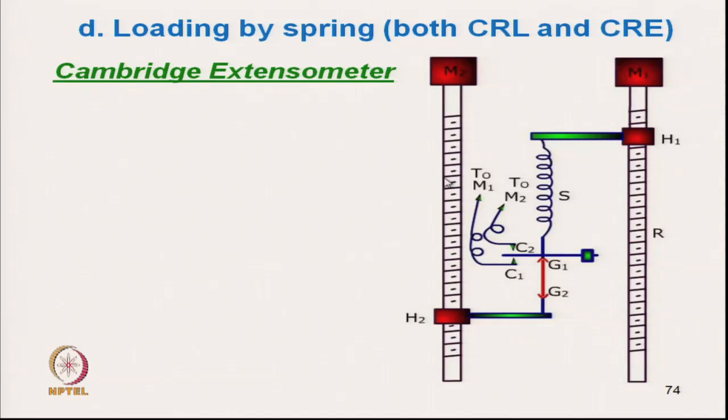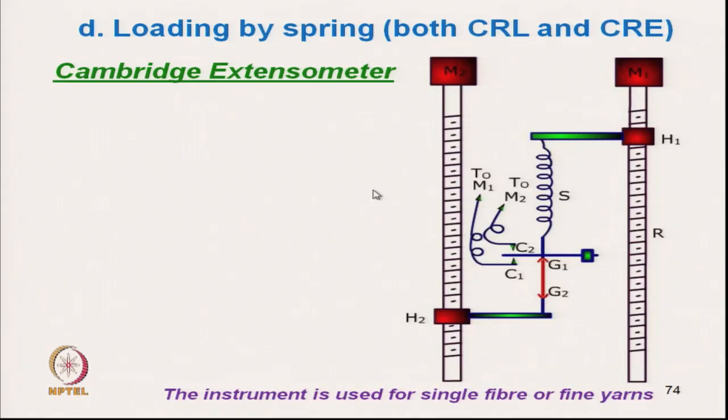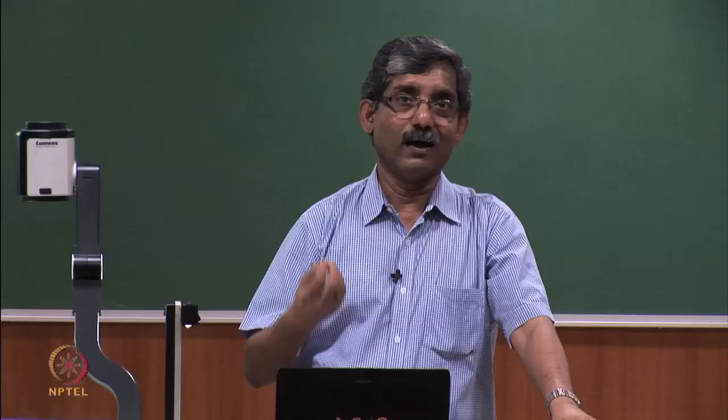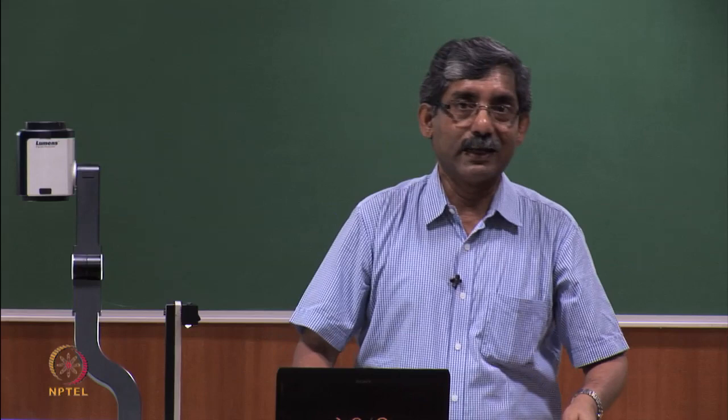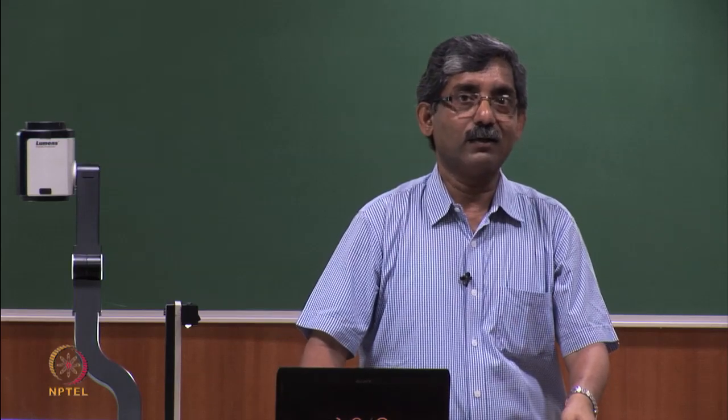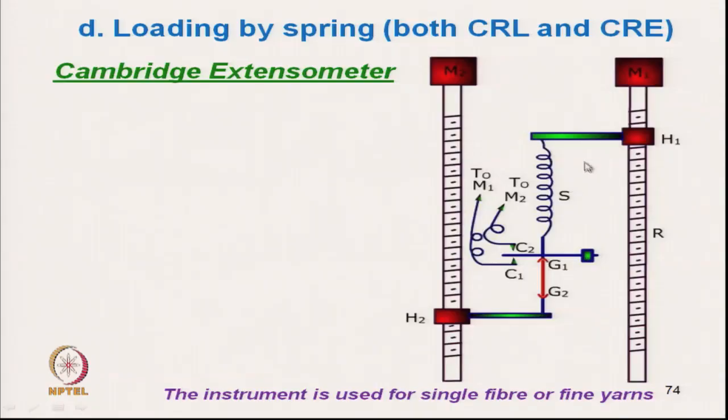Now, the principle is that here it is used for a single fiber or fine yarn. It cannot actually test very strong yarn; it tests very fine single fibers with lower breaking load, because here the loading is with the help of extending a spring. Okay.